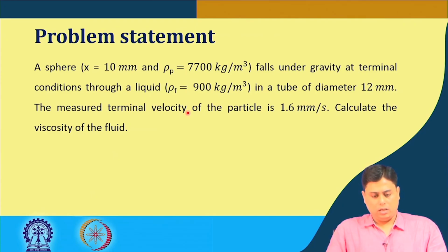So the point is this concept I have told you, that at first we have to find out, from the relation of either the previous two correlations that I showed you, either by Francis or by other correlation, what is the free fall terminal velocity in an infinite pool of liquid for such a spherical particle. If we can find that, then we can apply the Stokes law, and we can find out the viscosity of the fluid.